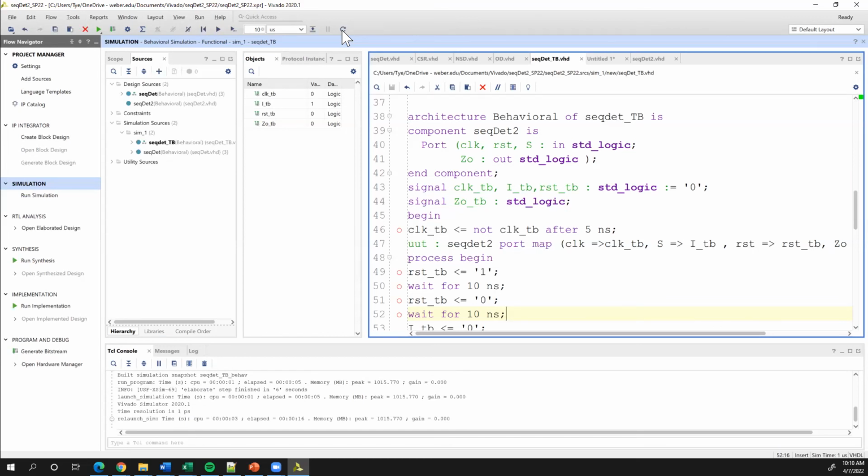So by the way, if you start running synthesis on an FPGA and it ever pops up with a message and it's like your ports are not compatible and it lists ports that aren't part of your top level module, it's because you've selected something else as a top level module other than what you expected. That's a problem that we see a lot.